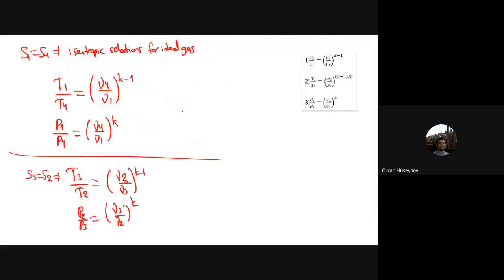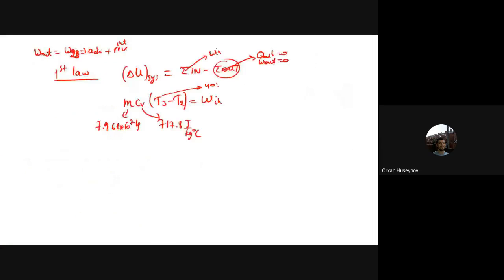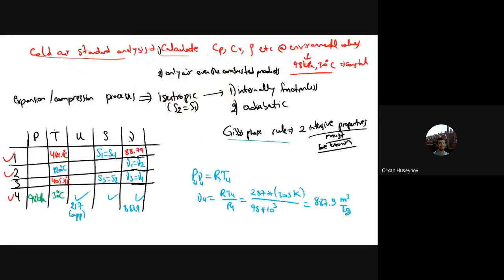The temperature value at state 3 gives 405.4 degrees Celsius. So 2 to 3 is an expansion process. I should look for the compression process, which is 4 to 1.